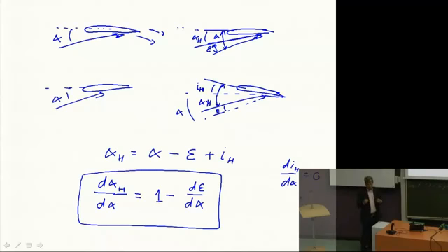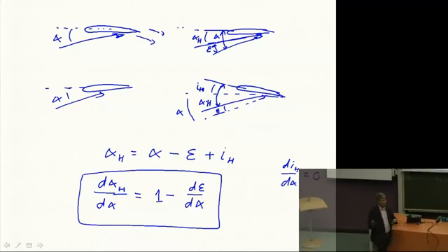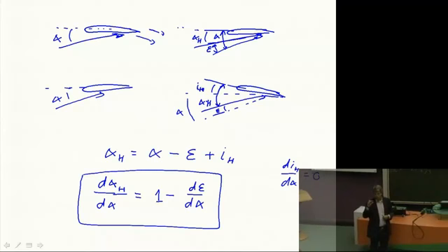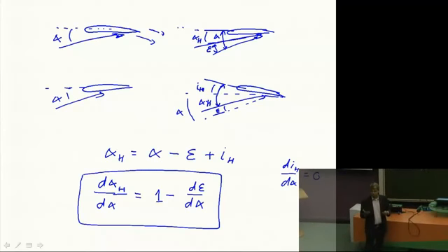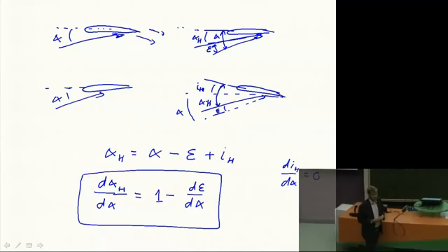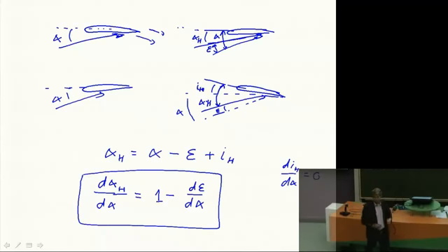So the pilot is flying, he notices that he has to pull all the time to keep the aircraft straight, then he will turn the trimming wheel, so the force will go away, and what it does basically is it sets the complete horizontal surface at a little angle up or down. And it doesn't move when a small deviation of angle of attack, for instance turbulence or something, occurs, because the pilot is not turning the trimming wheel immediately. At least we assume that he is hands-off.